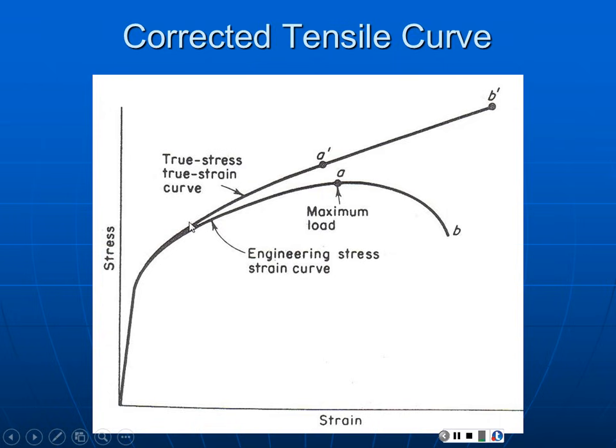And so the main reason we'll use true stress, true strain is you'll have opportunity, depending on which industry you end up in, to do design work with parts that are intended to deform permanently before they go into service. So it's called post-yield design. You may need to do this if you're talking about manufacturing processes where you're drawing or stamping metals or other materials beyond their yield point, in order to shape them. And so in that case, you need to know the true stress and true strain behavior of the material, and that's where you'll have cause to use these conversions and this kind of a stress-strain curve.